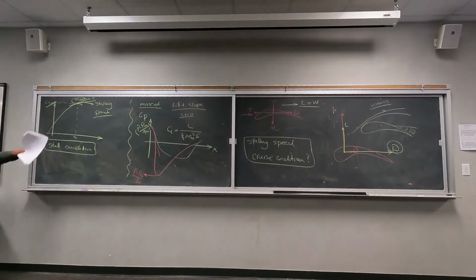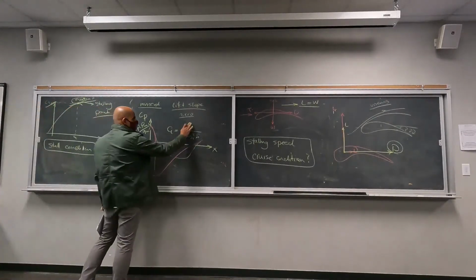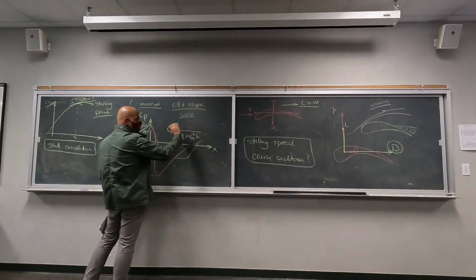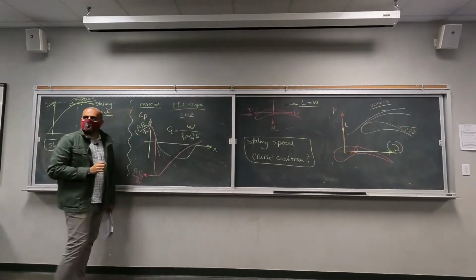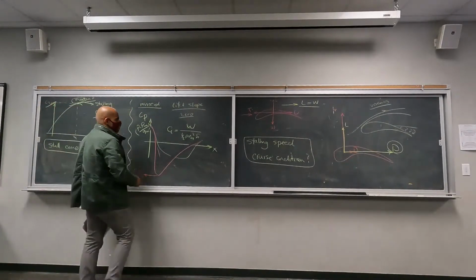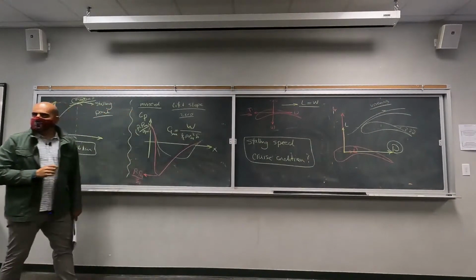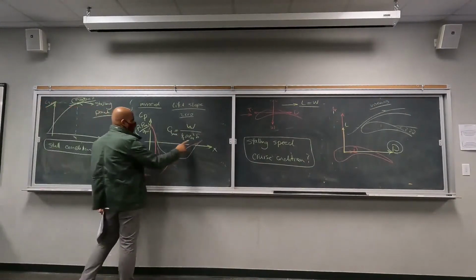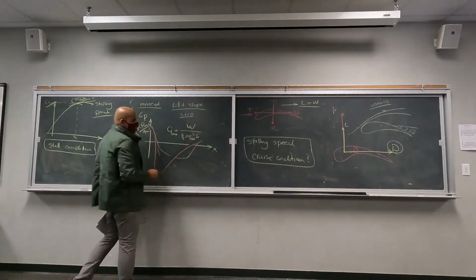What will happen to this equation during a stall? The cruise condition in general doesn't have anything to do with the stall. Your lift will equal weight, right? That's the idea, to maintain the cruise condition. But during the stall specifically, you are going to experience your maximum lift coefficient, right? And your velocity is going to become the stalling speed.